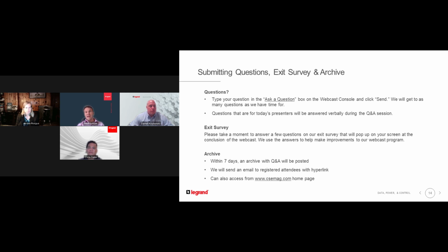Yeah, so when we're talking factory acceptance, that would mean that we are doing this out of Starline's factory. And we've developed a little system, we call it the APT machine. So it stands for Automated Plug Testing Machine. And this goes along with all of our busway as well, too. We will go through a series of tests. And typically what that means is for a plug-in unit, we will plug that up into a piece of sample busway. And we will hit this machine. And it runs through a series of about, I believe it's about 8 or 9 different pages of just tests, right? And it'll verify that it has the correct receptacle on there, the correct breaker on there. It'll check it with a serial number on the back. And it'll go through a series of tests.